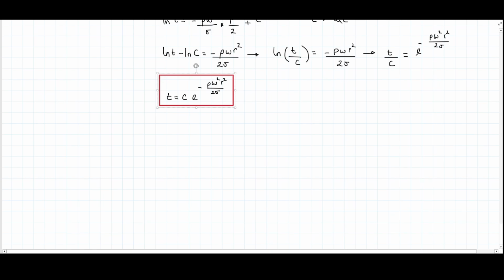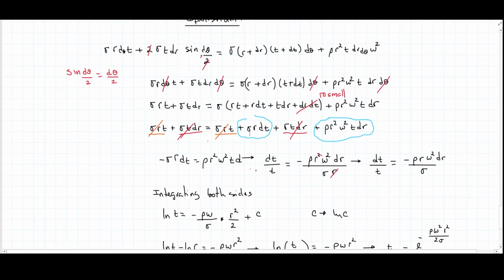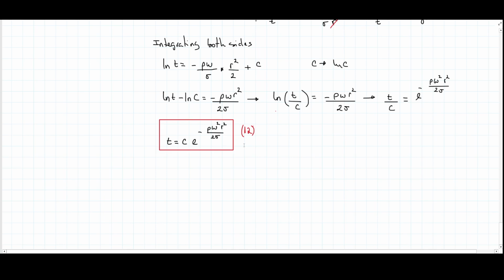So this equation is going to tell us how much the thickness should be, so we are always going to get a constant stress along the radial direction. If we want to solve this for the case that we are depicting here, I have an integration constant, so I need to use some boundary conditions. Let me write down here.